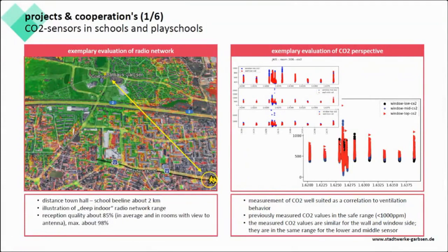We evaluated the transmitted number of telegrams and calculated the telegrams that should have been delivered in the focus time period and divided the 2 values. And although the network range shows no good reception, we calculated 85% delivery rate on average, and for a few sensors in the direct line to the antenna, we got rates of about 98%.